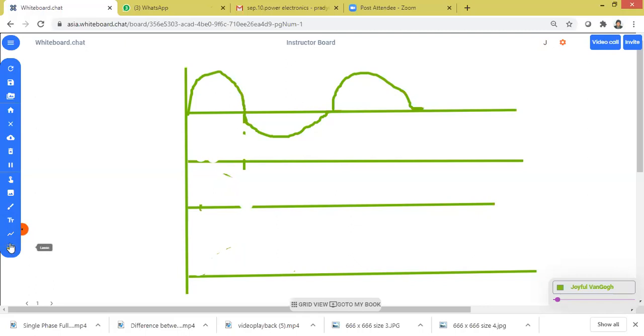One second, let us check this. Now, in order to have the minimum speed, I am selecting a firing angle greater than 90. Let us say I am selecting 120. Okay, here it is started. So when the firing angle is maximum, what will happen? Minimum energy is selected and minimum energy is transferred from input to output. So this is the minimum energy transfer.